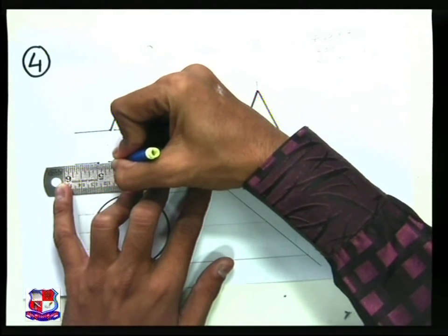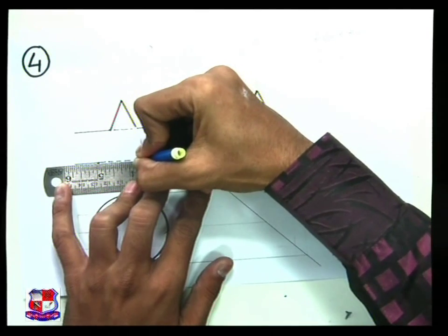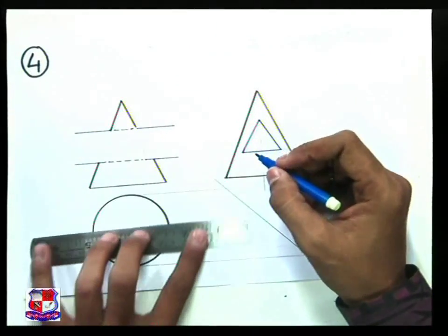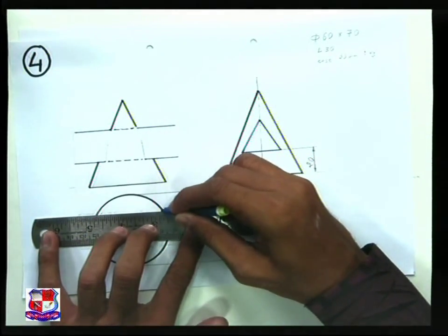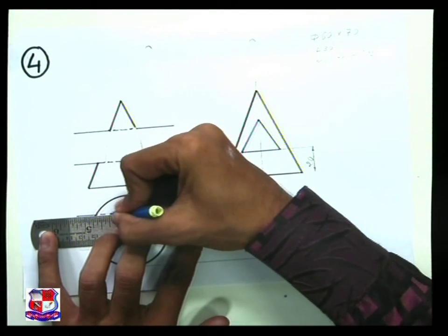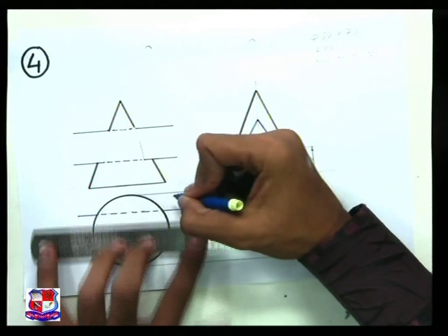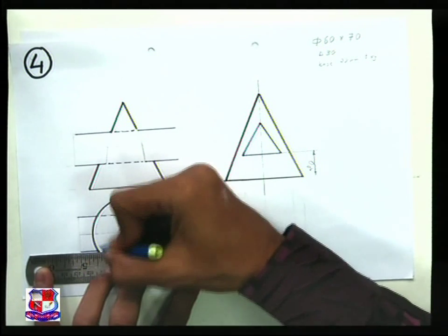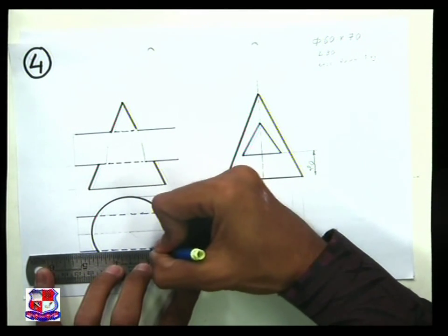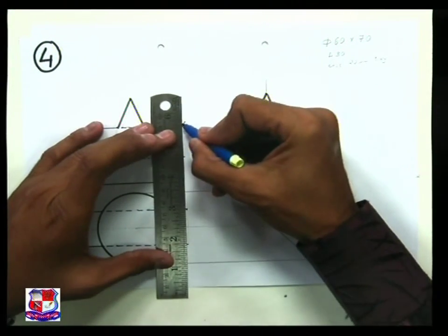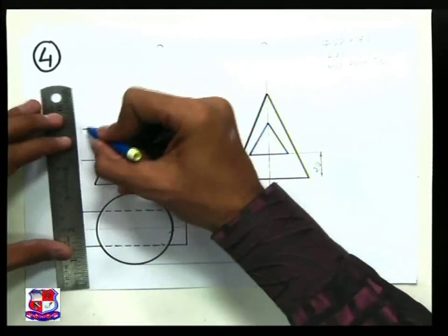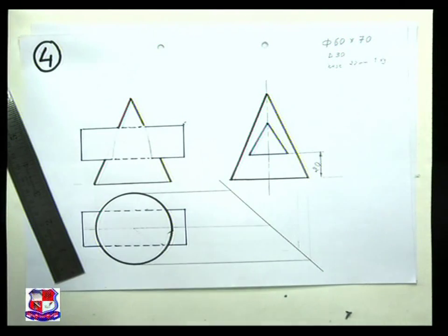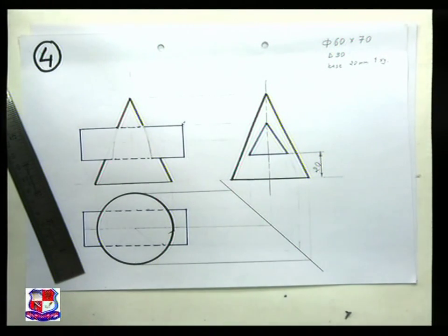From here to here, dotted line, dotted line. Here also it would be dotted line. And similarly, by taking projection, we can draw its top view, and inside this cone the edges could be represented by the dotted line, as it is not visible, like this, right? And these are the ends, bases, circular faces of the cylinder, represented by lines in the front view. So this is the given data.